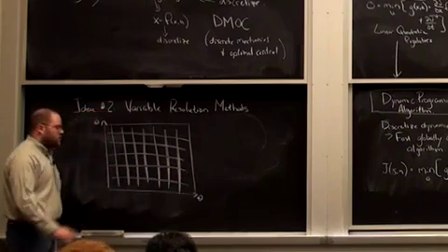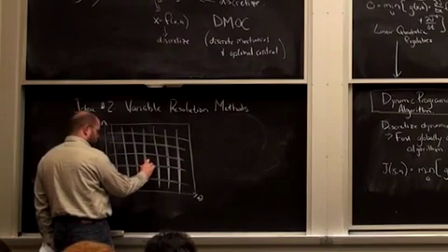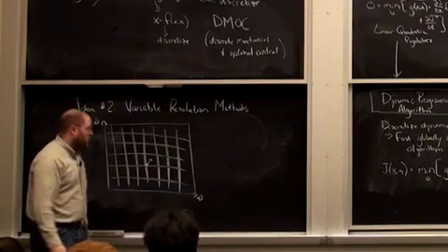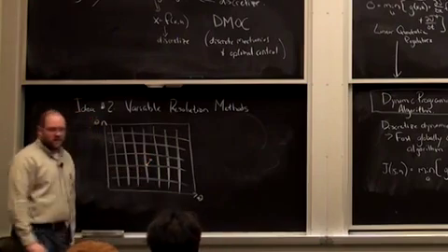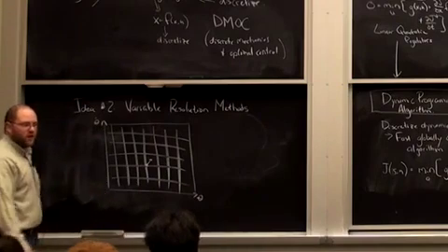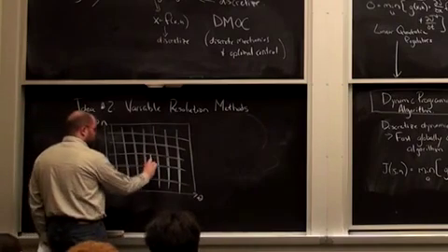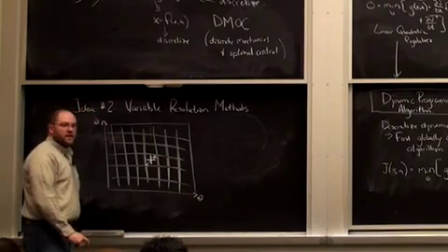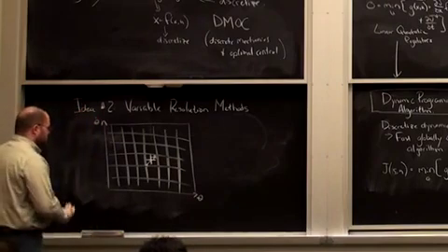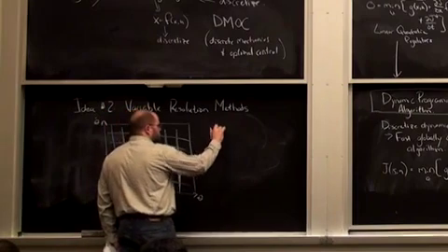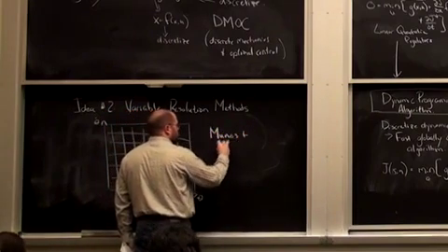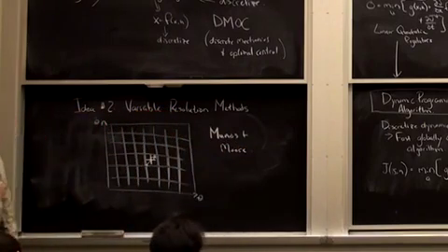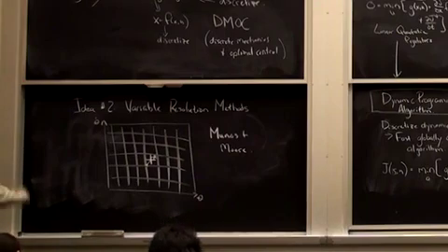and you do your optimal control solution on this, and you find out, for instance, that when you're transitioning from this point this way, energy is not conserved, or the value function at these corners are very, very different. So it looks like there's something more going on there. Then let's just add more resolution there, right? As much as necessary to capture the dynamics. There's a nice line of work in this by Munos and Moore, the same people I listed for the barycentric interpolation. They talked about variable resolution DP methods.